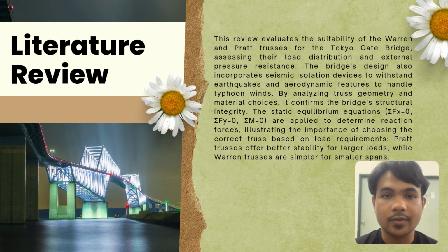To analyze the forces acting on the bridge, use static equilibrium equations. Total Fx equals 0, total Fy equals 0, and total moment equals 0. For example, in a simply supported beam with applied loads, reactions can be calculated using these principles. Free body diagrams are crucial in visualizing forces and reactions in structural analysis.